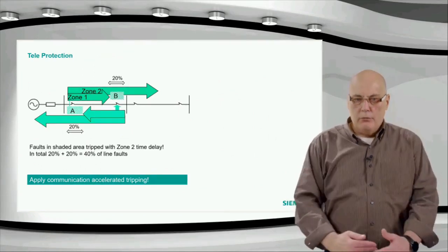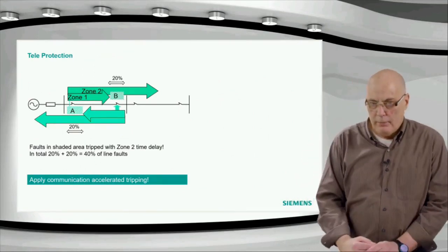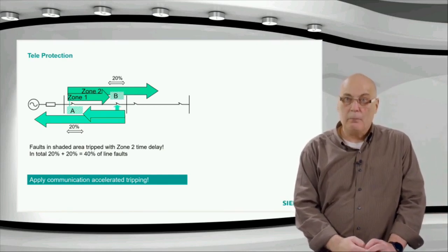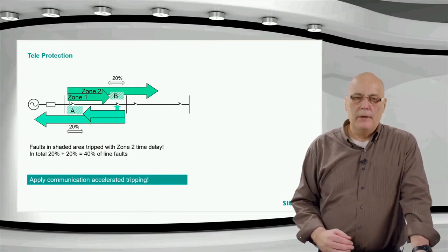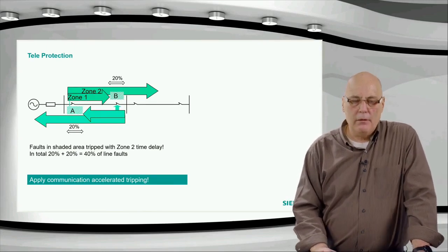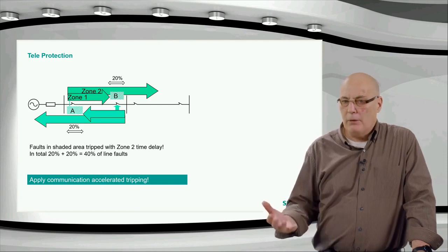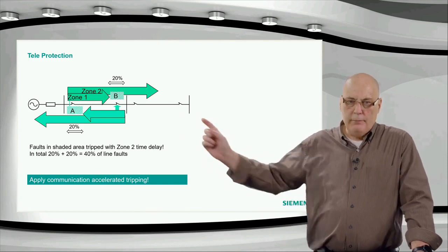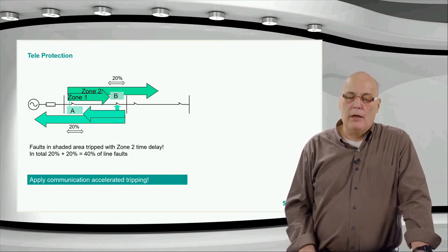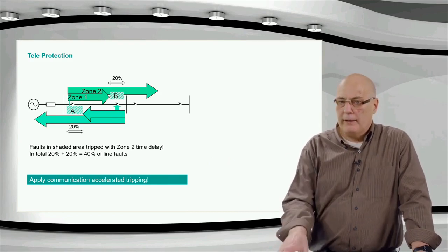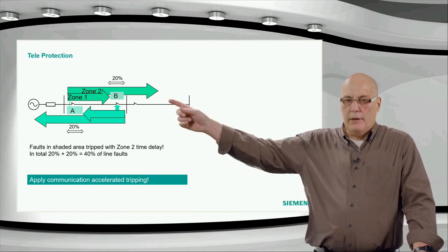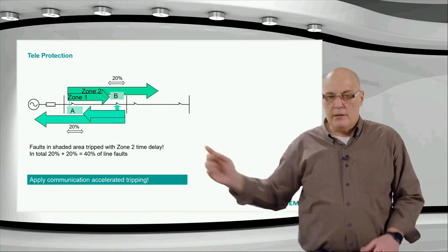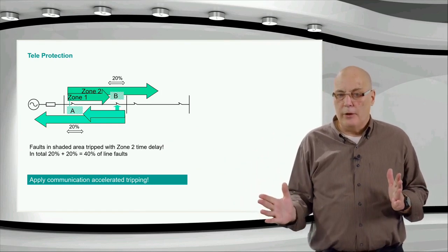All right, that brings us really to, I think, our final topic that we want to talk about this morning, which is teleprotection. The teleprotection is a very effective supplement or add-on to the distance protection. What can we see here? We can see here a normal line, and as we saw this morning, the zone 1, typically 80%. That means you've got that safety margin over there, B, and a safety margin A from the other side. Both of those are about 20%.